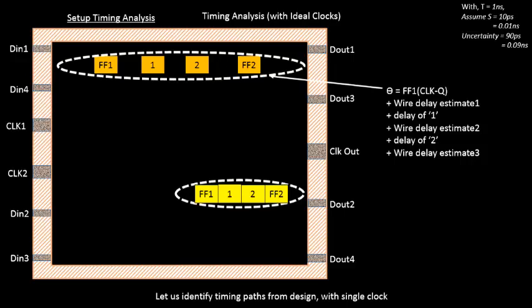Hello everyone. Let's continue our discussion on the flow. So the next step after the optimized placement stage is to do a timing analysis with ideal clocks. The reason to do this is to get an idea of how the timing looks at this stage.